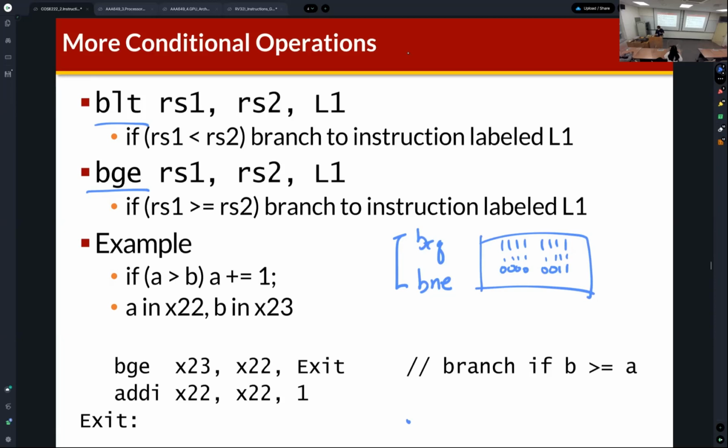What is the exclusive OR gate? It has inputs A, B and output C: 0 0 gives 0, 0 1 gives 1, 1 0 gives 1, 1 1 gives 0. The output of exclusive OR is 0 if A and B are both zeros or both ones, and if A and B are different, it becomes 1. So for checking the equality of two operands, we can simply use an exclusive OR gate.